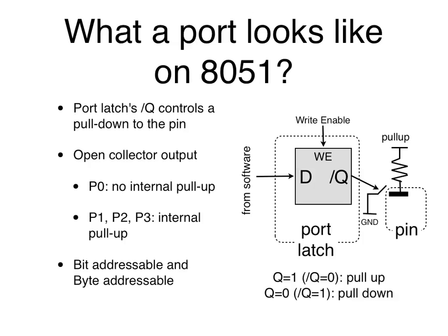And this switch on one side is connected to the ground. The other side is a pull-up, okay? So when you press it, which is like when you set Q equal to 1, Q bar is 0. So that means it's disconnected, that you're not pressing it. When Q is 0, what happens? Then Q bar is 1, and 1 means pressing it, and that establishes the path to ground, and that pulls it down. Okay? We'll see a few slides to do this.